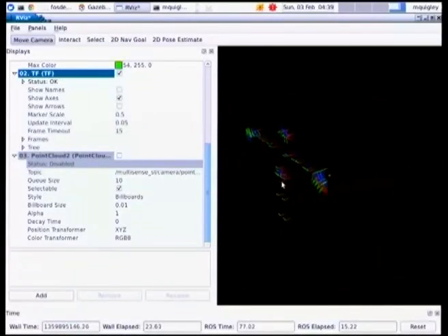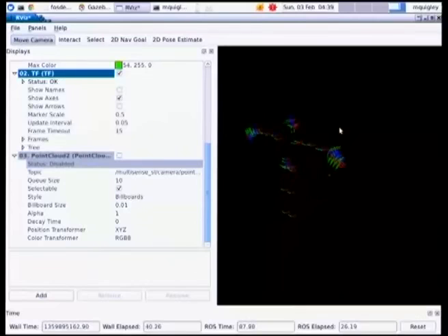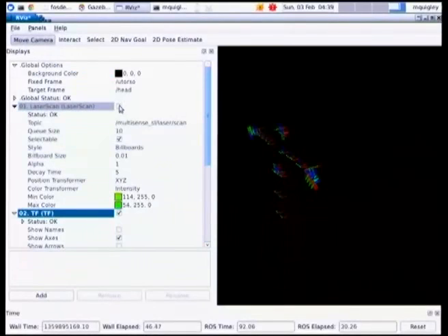So again, as mentioned before, this stuff is supposed to be general to many robots. This whole visualization tool was actually written for the PR2 robot at Willow Garage, but has since been used by many things. It really is just looking at ROS messages and putting them in an OpenGL framework. And so that's why it works with any subsystem that you or anyone else will write around the world for ROS-based robots.